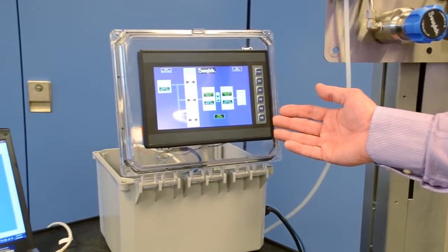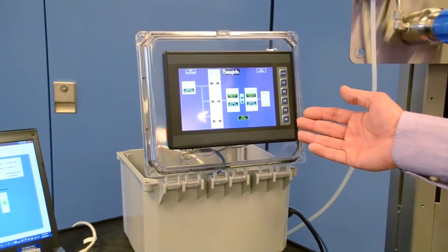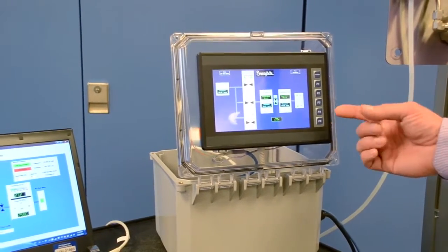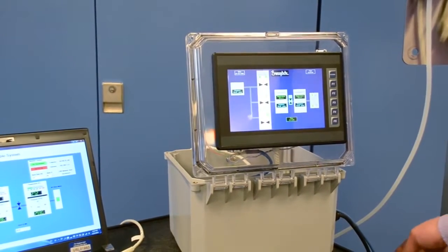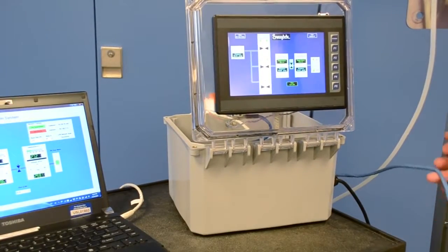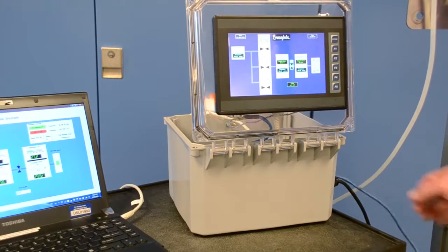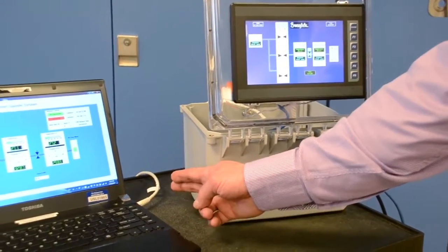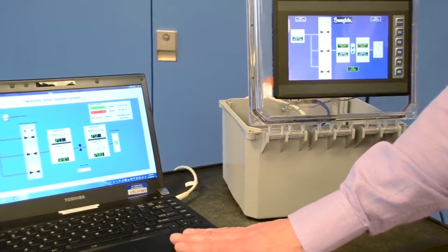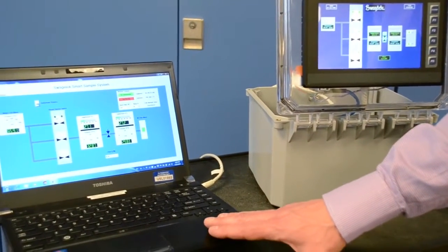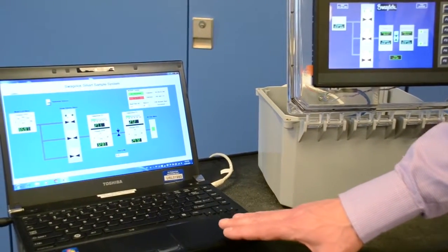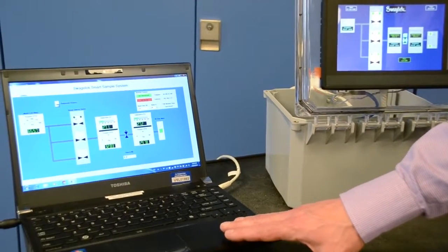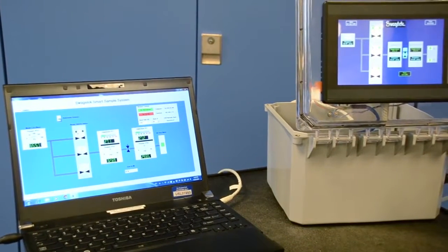The OCS, or operator control station, serves two primary purposes. One, it takes CANopen information from the sample systems and makes it available on Ethernet so that a computer can access it easily, actually from anywhere in the world. Once we're on Ethernet, we actually have worldwide web access to the sample systems.